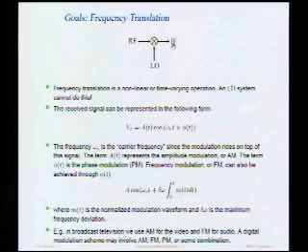We draw them as a circle with an X to emphasize the fact that they're taking a product. Not strictly valid, but it's a good first-order approximation. If I take the product of two, let's say, cosines, the output is a cosine at the sum frequency and a cosine at the difference frequency. So certainly products are a way to build mixers. Some terminology: usually for a down conversion system, meaning we're going down in frequency, like in a receiver, we have an input RF frequency, and generally we have an IF, or intermediate frequency, which is lower. And in order to generate that lower frequency, we use what's called the local oscillator, or the LO frequency.